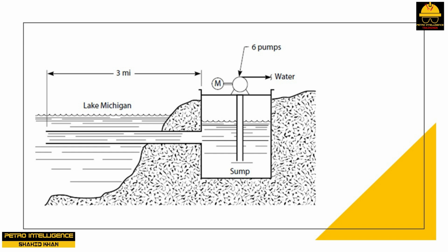To accelerate the water in the pipeline to 8 feet per second requires more energy than to keep the water flowing at that same velocity. And this extra energy comes from the extra 3 feet of elevation difference between the water level in the sump and the water level in the lake. Once the water has reached its steady-state velocity of 8 feet per second, the need for this extra conversion of feet of head to acceleration disappears, and the water level in the sump rises to within 12 feet of the lake's level.